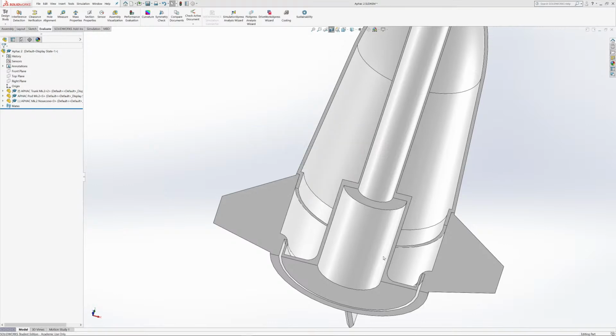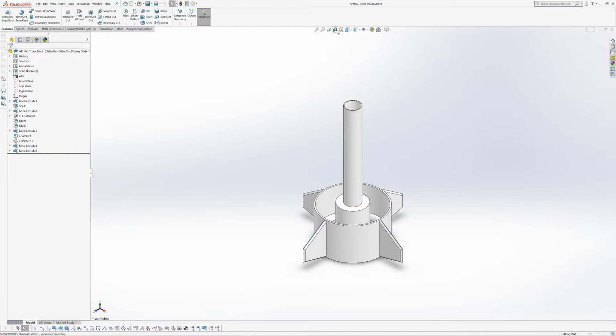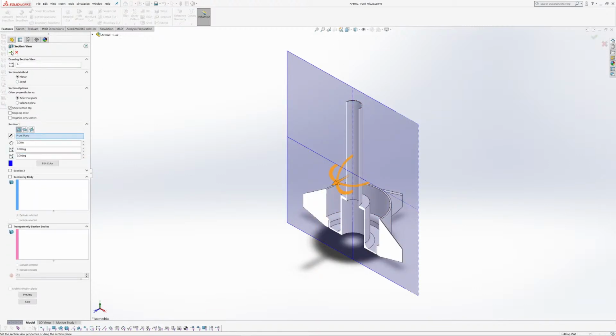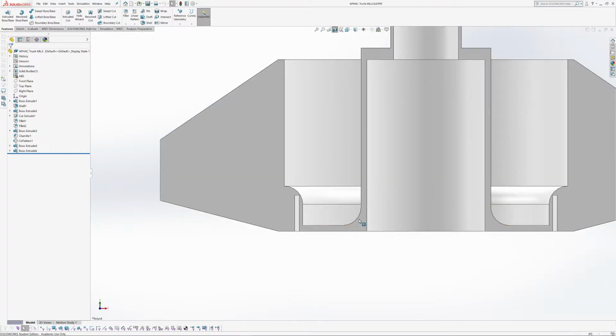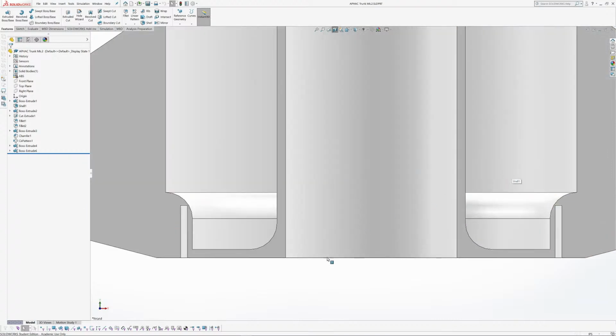And the reason why we had to add this fillet here was because when you're printing, you print it in layers across the screen here, horizontally, and so the connection between this tube and the rest of the vehicle was pretty weak, because it printed along the layers, and the layers are weak to lateral force along the line of the layer.